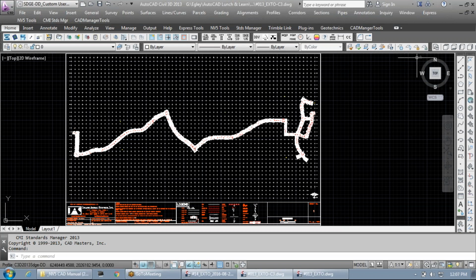We talked a little bit about efficiency and elevating our game. We had some conversations about slowness of files, making sure we're utilizing the files and the Civil 3D data correctly. We talked about the EXTO drawings, your EXTO and your EXTO C3 file, and what should be in each. If this is what your EXTO looks like, you've got major issues, because this has all kinds of break lines and Civil 3D data that you don't want being XREF'd into every single drawing.